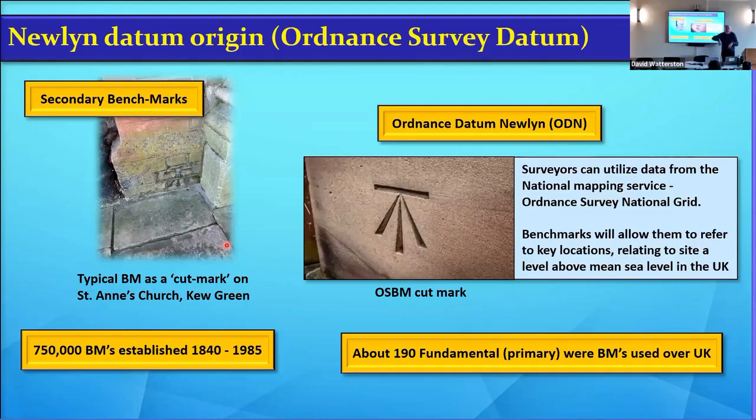The height of Everest is only out by a few feet, and they got it 200 or 300 years ago. So old survey methods and principles are pretty good. To get the benchmarks, they had these trig pillars. So then they levelled them and they said that's the primary network.